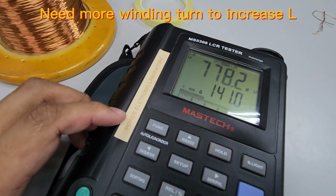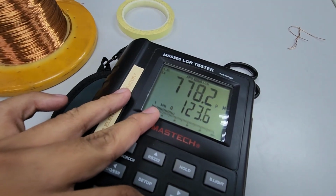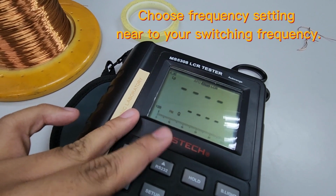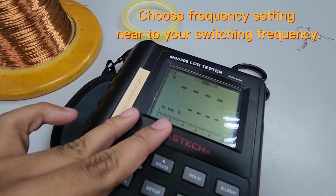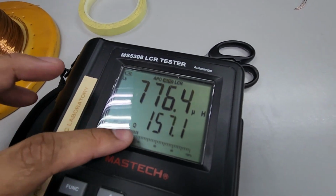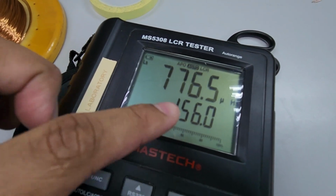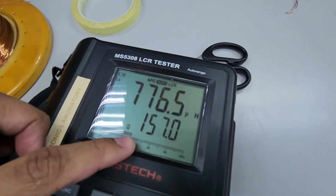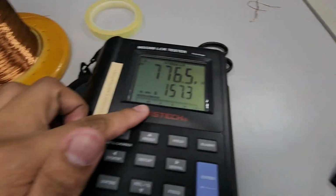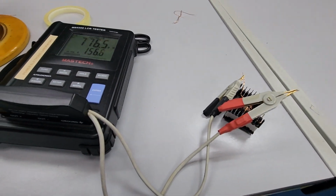You can also check the frequency, try to choose a frequency that is near to you. 100 is too high, maybe 10 should be okay. Okay, 10 kilohertz, and the Q is 157. If your winding is quite good, I think the Q is higher, if I'm not mistaken. So this one I think is very bad. But for your case, make sure you do it correctly. For me, I just demo it. So that's it. That is how you make an inductor.